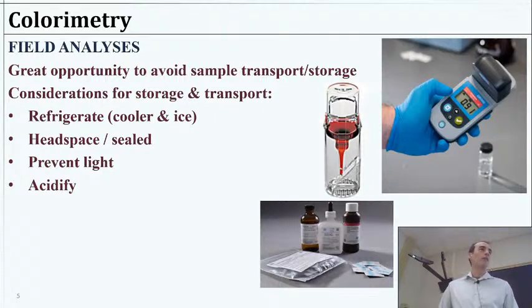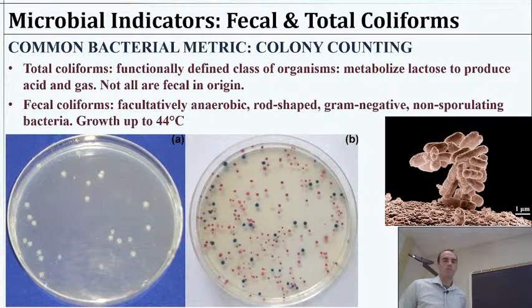Sometimes maybe you need to acidify or perhaps occasionally add base to prevent some reactions from occurring, or to stabilize, or to prevent precipitation. Certain things based on your sampling needs, maybe you have to do that as you collect the sample. So several things to just be thoughtful about in preparation for doing field sampling.